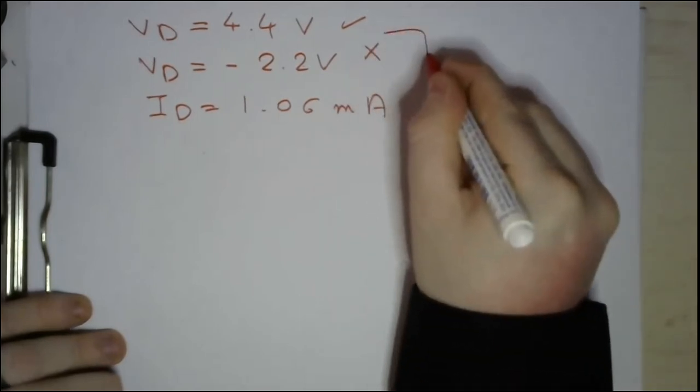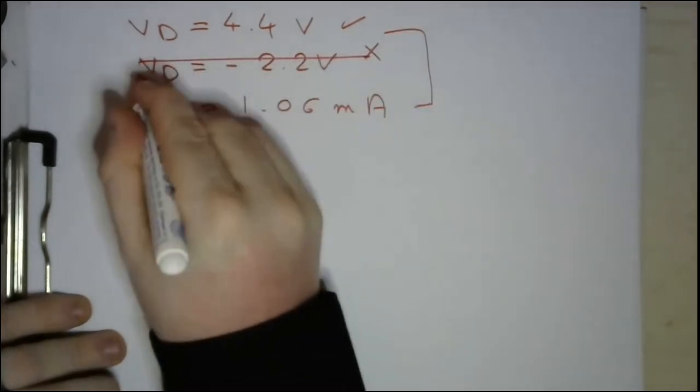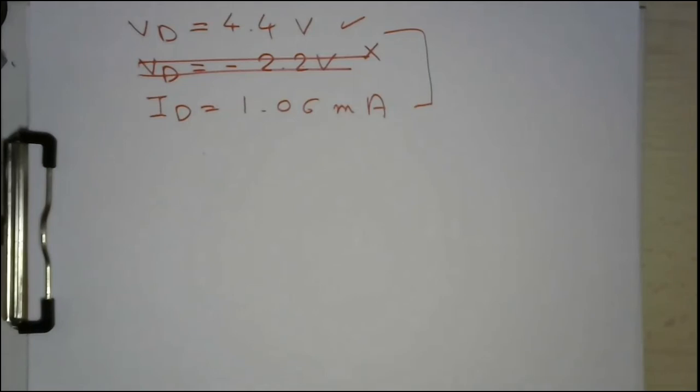So now this is ID and this is the VD. Okay, so is this the termination of the DC analysis? No. In order to terminate the DC analysis, you should end it up by calculating what we call the gm, the transconductance.